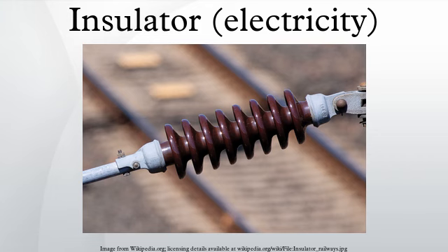Strain insulator. A dead-end or anchor pole or tower is used where a straight section of line ends, or angles off in another direction. These poles must withstand the lateral tension of the long straight section of wire. In order to support this lateral load, strain insulators are used. For low-voltage lines, shackle insulators are used as strain insulators. However, for high-voltage transmission lines, strings of cap and pin insulators are used, attached to the cross-arm in a horizontal direction. When the tension load in lines is exceedingly high, such as at long river spans, two or more strings are used in parallel.